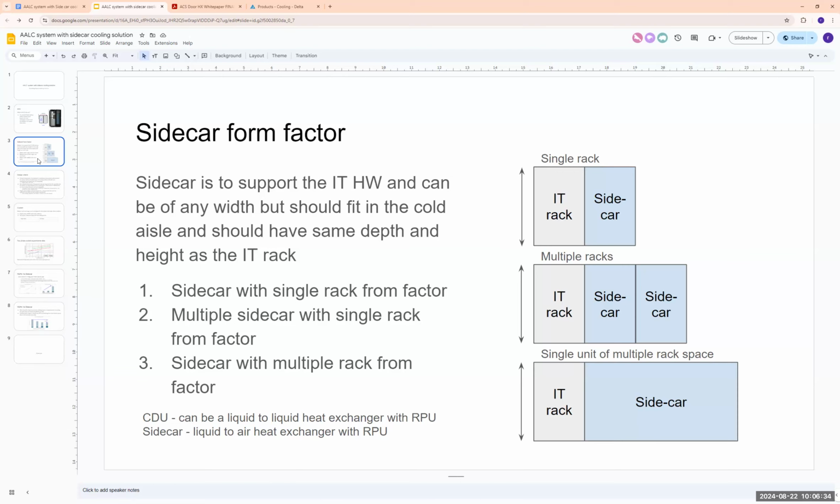And whether you are using water in the cold plate or 2-phase refrigerant, at the end you have the same heat transfer units, the same heat transfer through the fins, usually 2, 3, 4,000 watts per Kelvin square meter. For both technologies it is almost the same.